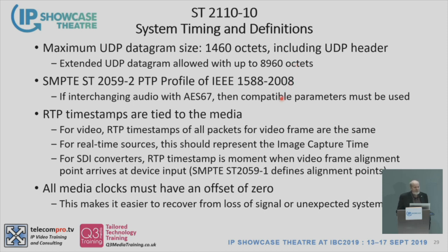We have precision time protocol. That's called out specifically in 2110, and that's how timing works. You must have PTP on your network to support a true 2110 based system. The RTP timestamps are tied to the media, so each packet that comes out gets a time stamp based on the PTP clock. The different RTP clocks advance at different clock rates, audio versus video, but you can relate them all back together using PTP.